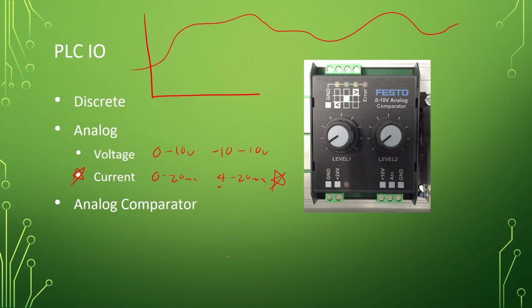So when you have a resistor and, let's say, 10 milliamps flowing through it, and the resistor value is 5 ohms, you can do V equals IR. We measure the voltage here and put my voltmeter there. I know there's 5 ohms of resistance, and I know the voltage, so I can now calculate the current. So we actually can still do it with a voltage measurement. It's really nice. But that only works if we know very accurately the value of that resistance. That is something we need to take into account.